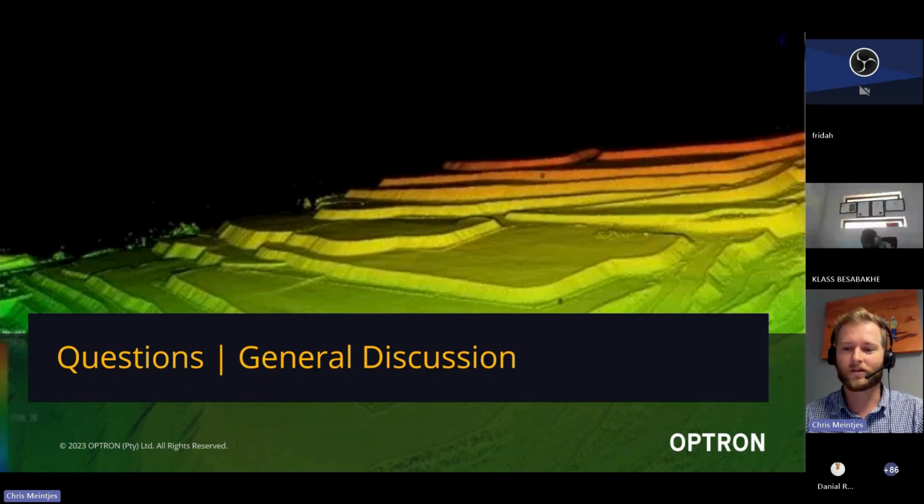Individual CAD points in Trimble RealWorks? I don't think so. So in TBC, as you saw, I took the point cloud and broke it down into CAD points, which can then be exported into a CSV, into a DXF. In RealWorks, you're working with the point cloud as a whole. You can also export that point cloud as a DWG, where you can then extract the points.